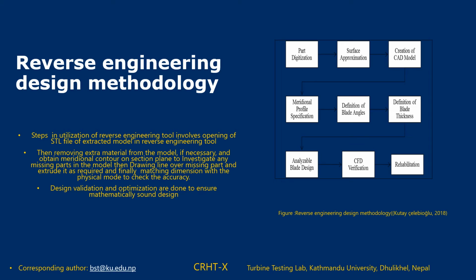After we are able to extract a CAD model, we do a meridional profile specification, then we define a blade angle, then a blade thickness, then we analyze and try to validate it in CFD software, then we finally manufacture. So these are the basic reverse engineering design methodology steps involved in remodeling of an eroded Francis runner.